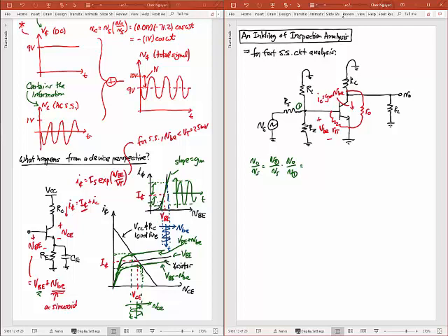And all I'm going to do is multiply those two gains, but when I calculate these gains, I have to make sure that when I go from Vs to V1, I'm accounting for loading by the next stage. So Vs to V1 is going to these resistors, but the next stage is this transistor. I've got that R-pi loading this thing. And so at this point, I can say that if I look in this direction here, if I look in that direction there, and let me move this a little bit below to give myself some space.